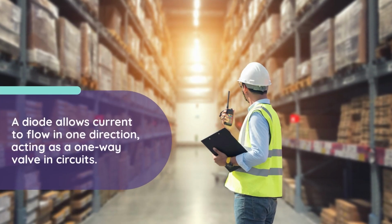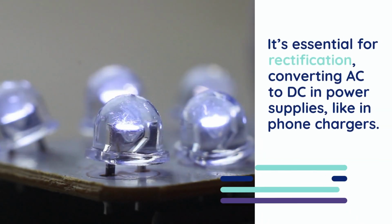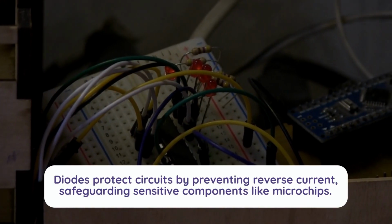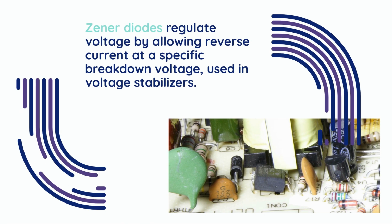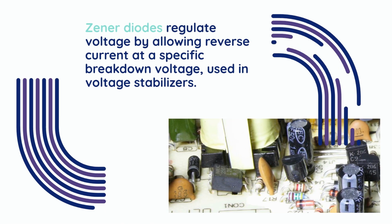A diode allows current to flow in one direction, acting as a one-way valve in circuits. It's essential for rectification, converting AC to DC in power supplies like in phone chargers. Diodes protect circuits by preventing reverse current, safeguarding sensitive components like microchips. Zener diodes regulate voltage by allowing reverse current at a specific breakdown voltage, used in voltage stabilizers.